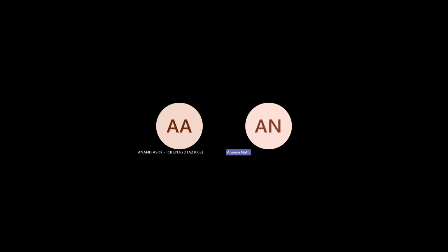In DED, directed energy deposition, from the tool, which is the nozzle or the cladding head, the powder and the laser both come at the same time. Whereas in LPBF, only the laser comes from the galvo scanner and F-theta lens. So the tool is different for each process, and that's why the tool path will be different for each process. Now, how the tool path is defined is based on how your geometry is.